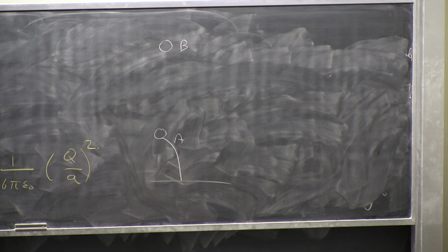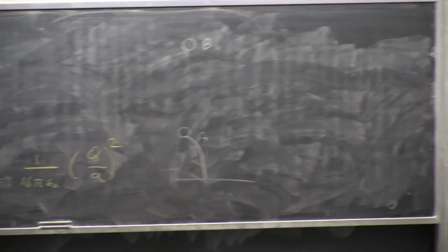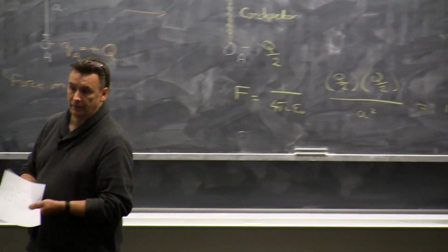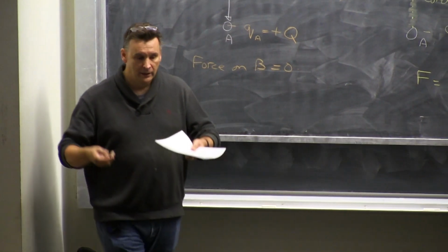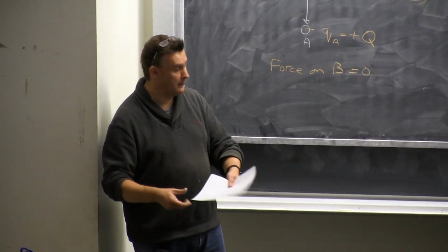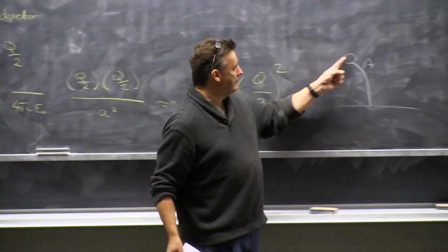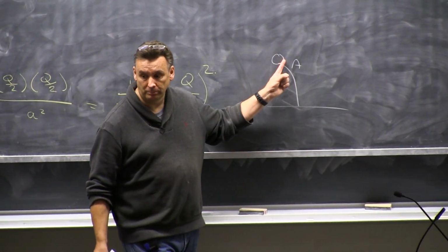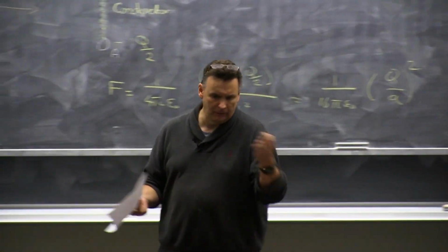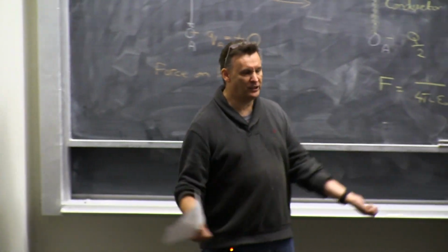This is a concept that will come up again and again, and it's worth spending a couple of minutes talking about it. We assume that the earth is very large compared to anything that we're doing experimentally, and it's electrically neutral. There's so many atoms in the earth that all the positives equal all the negatives. So there's 0 charge there. So it's a sink. And because it's such a large 0 charge, if I connect anything to that, it also becomes 0 charge. It leaks away maybe 3 or 4 electrons. In the scheme of the size of the earth, that's nothing. So I assume that that's 0.